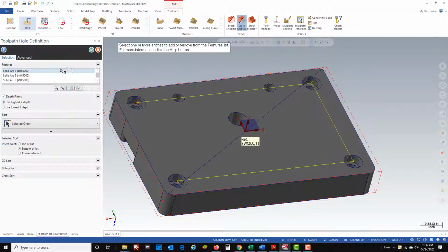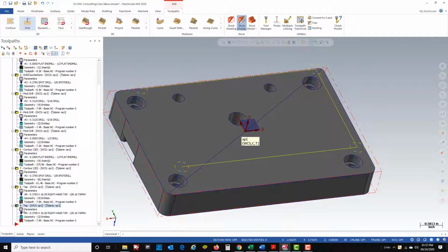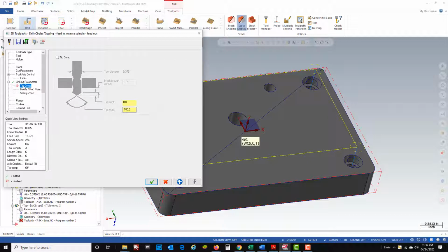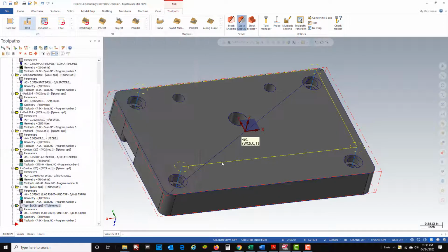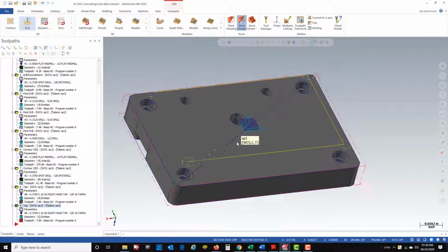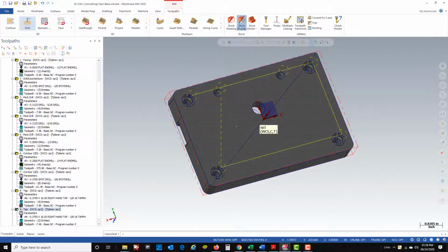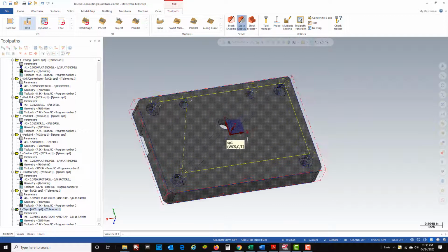I'm going to go ahead and change the geometry to these other 2 3/8-16 tapped holes, and I'm going to make sure these do go through the part. So I'm going to go back into my linking parameters, and I'm going to tell it to go 900 deep and turn my tip comp on. So you want to make sure you have at least 1 inch of threads on your tap, which most 3/8-16 taps should be able to go that deep. That'll tap these holes all the way through. This is what you want because we're actually going to be bolting in our pins from the front side. So calculate that. Now our part is fully programmed.